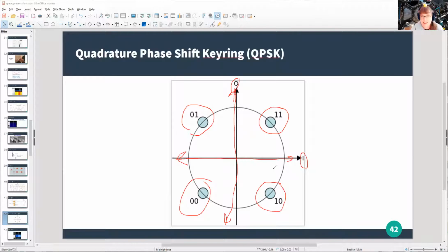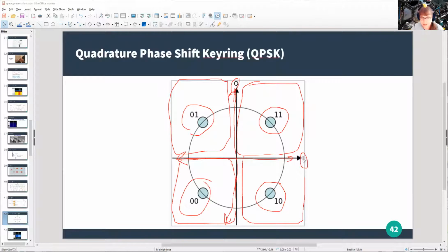And the nice thing about this is that if there's a lot of interference, that's fine, because you have all this space over here to deal with interference. The more advanced these things get, the less resistant they are to interference. But for a BPSK, which is just 2 sides, and QPSK, which is the quad, the 4 squares you see, they're very immune to interference. But you can encode a few bits at the same time. So you can get a lot of data through using these types of encoding, using phases.